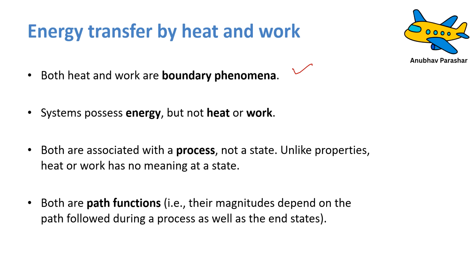The candle was burning inside an insulated room, right? There is no heat transfer taking place, though the temperature within the system is changing, and many things are happening within the system. The system possesses energy but not heat and work. We have to understand this energy is a property of a body, but heat and work are not properties. They are not properties of the body, they are energy in transfer.